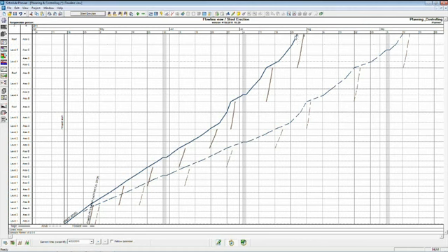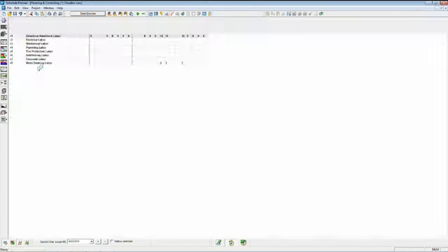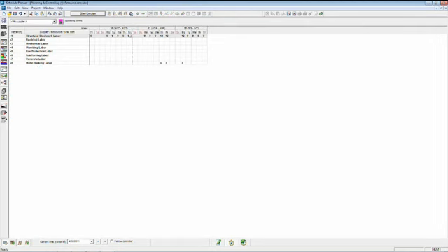But whether or not the steel installer is actually showing up with 9 guys, that should be part of the weekly actuals tracking. So you're going to track your percent work complete, and you're going to track the men that are working. So the number of guys by activity can be tracked within the system as well. It's called a resource calendar.